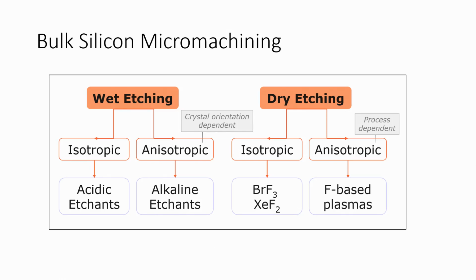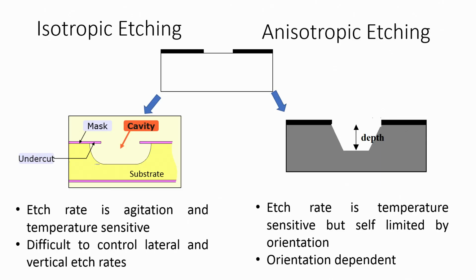The gases will etch the silicon, and for silicon we generally use C4F8 and SF6, while we also use helium and oxygen in the case of deep reactive ion etching. We will see a video of how a deep reactive ion etcher from STS can be used.